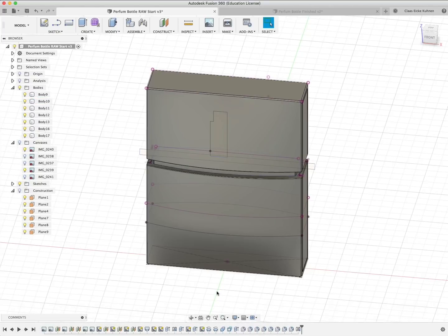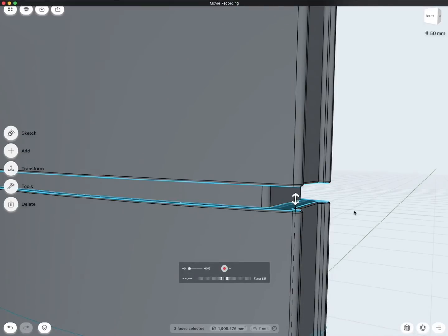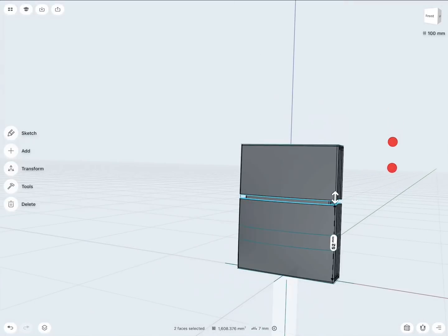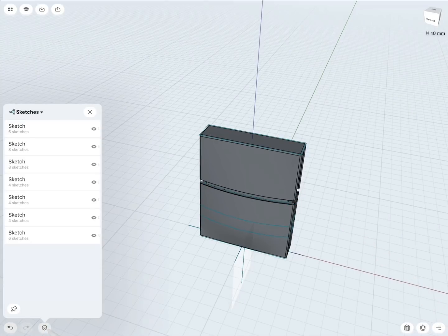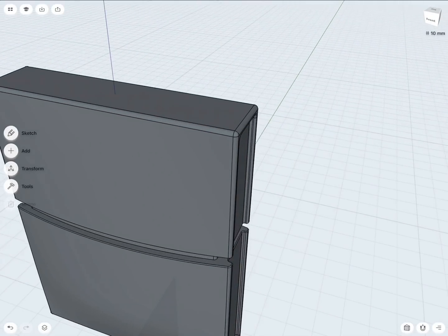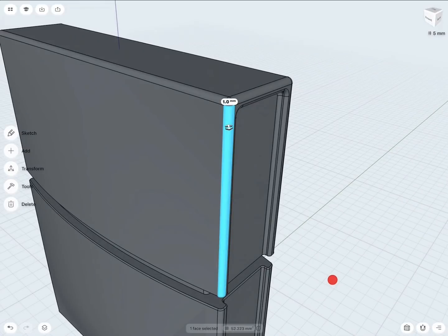And that is just the problem of parametric modeling. You have to be very, very specific, and you can't change things so much. In direct modeling, again, we use the sketches, but there are no association to the sketches and the modeling feature, and then we can adjust all the geometry simply via direct modeling commands. Now, as you saw with the fillets, if I select this fillet, I get the command to adjust it.